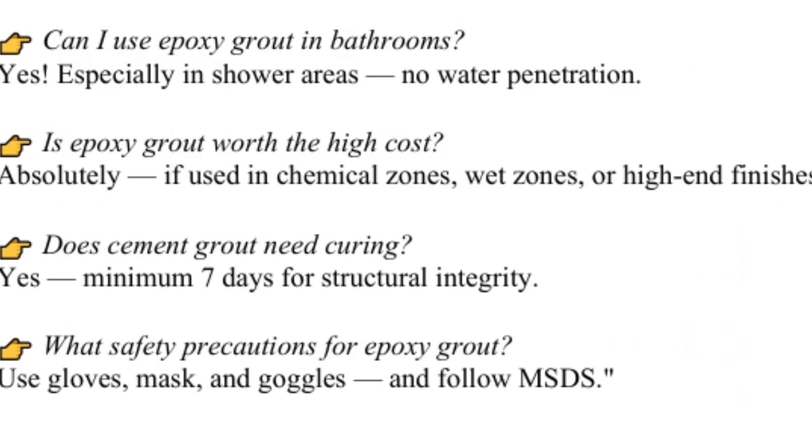Now, you may have some questions in your mind, and I have covered some of them. Can I use epoxy grout in a bathroom, especially in shower areas? Yes, and there will be no water penetration. Is epoxy grout worth the high cost? Absolutely. If used in chemical zones, wet zones or high-end finishes, go for the epoxy, but it is a high cost.